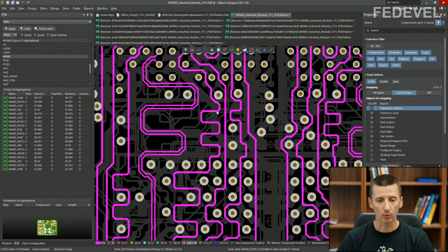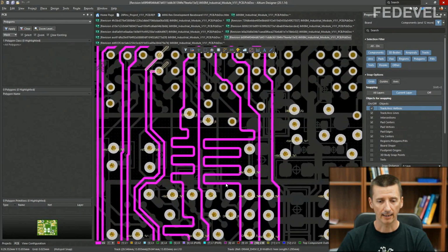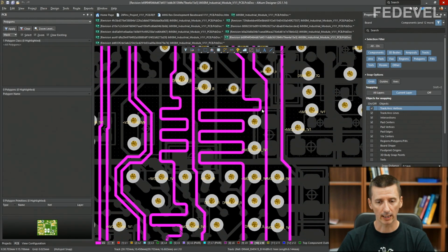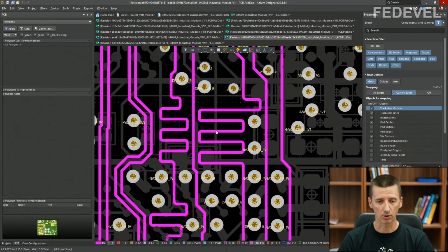When I asked him to do this length matching, this was actually the initial layout, and I pointed out that when you are creating these waves, you would like to also keep maybe some space between them, okay? So this is how it looks when it is improved. The space between the waves is much bigger than what he initially created.